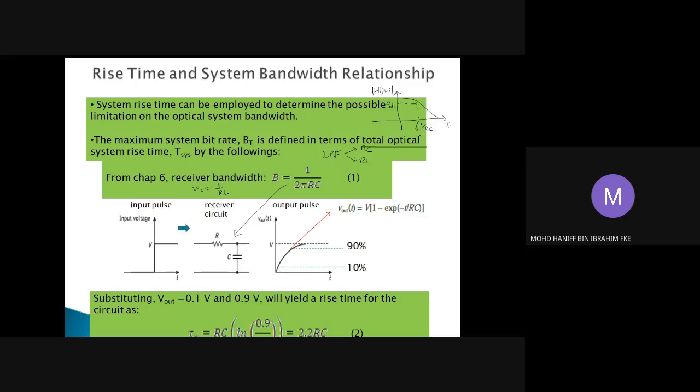That should be your omega c, equal to 1 over RC, and we then have FC equal to 1 over 2 pi RC. So basically this is your bandwidth. The bandwidth of the system is a 3 dB bandwidth. That's the reason why we have the bandwidth of 1 over 2 pi RC.